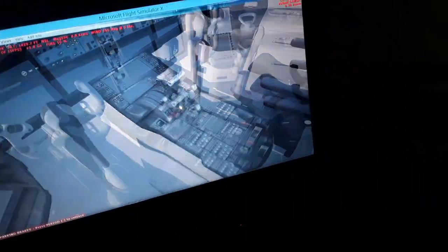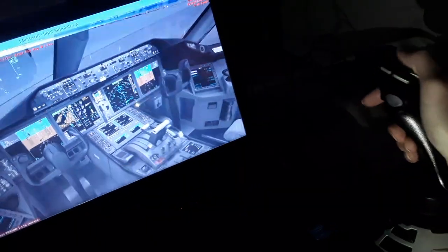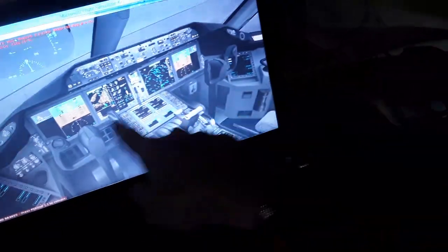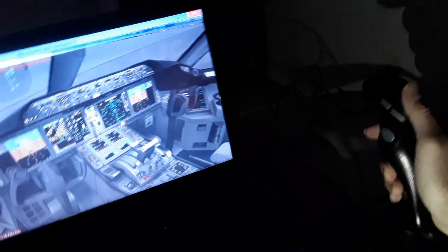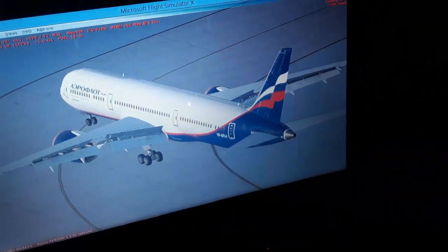So we have here, you can see the elevator for climb descent, side stick back and forth in the Airbus, control column back and forth in the Boeing. Both sides are interconnected in the Boeing aircraft, all flight controls together, unless you have a failure. Also we have one more axis besides the pitch axis and the yaw axis. This is the longitudinal axis from nose to tail, transverses all the other axes, is the side stick left and right in the Airbus aircraft.